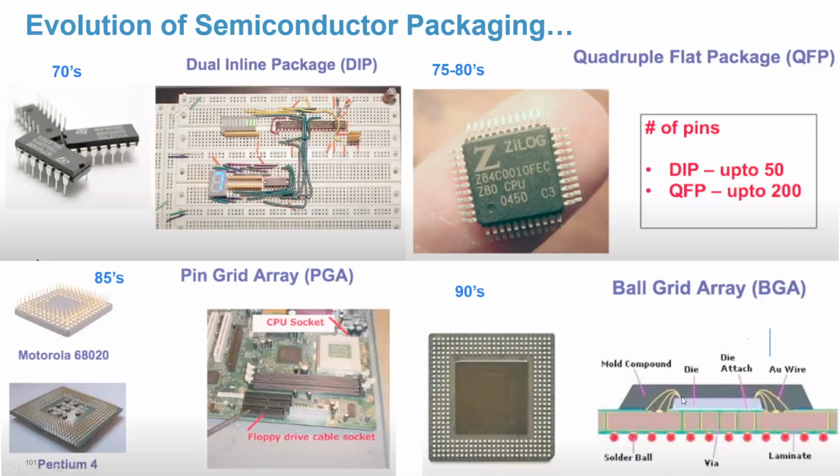image that I've got here, where in the schematic you can see there is a die, and then there are connections being made from the active surface of the die. The active surface is on the top. And from there, you are taking these wire bond connections onto the carrier. So basically, the ball grid array is a carrier board on which there is a die, with a molding compound or epoxy to seal the die.